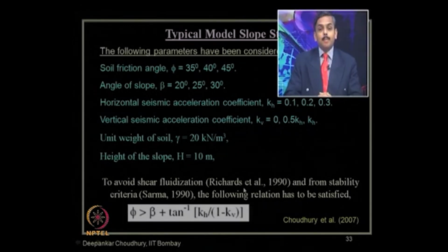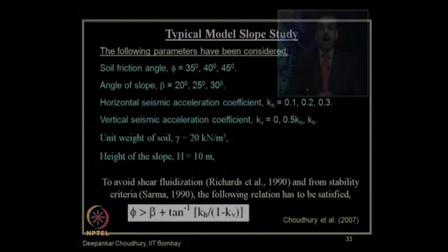said, they mentioned that even a dry cohesionless soil, like we know about the flowing of a soil after liquefaction occurred in case of cohesionless soil in saturated condition. But if the cohesionless soil is completely dry, then also it can flow like a fluid.